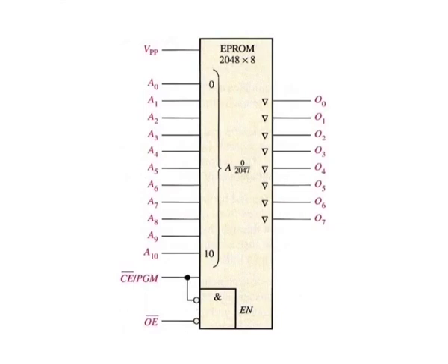Its operation is representative of that of other typical UV EPROMs of various sizes. As the logic symbol shows, the device has 2048 addresses, that is 2 to the power 11, each with 8 bits. Notice that the 8 outputs are tri-state.